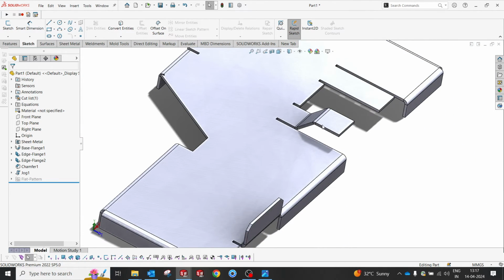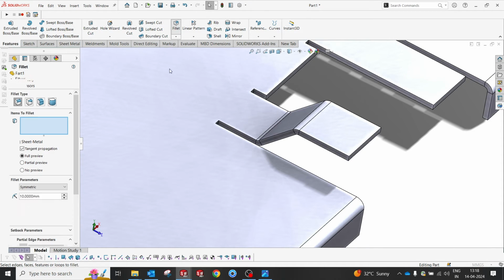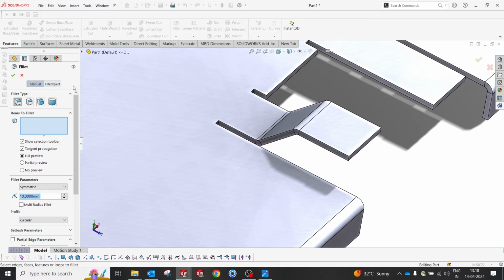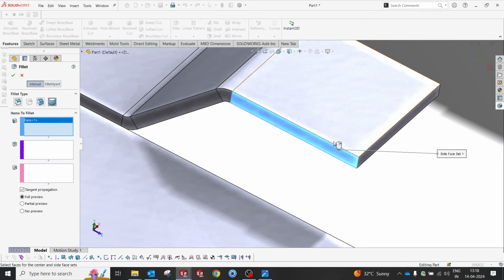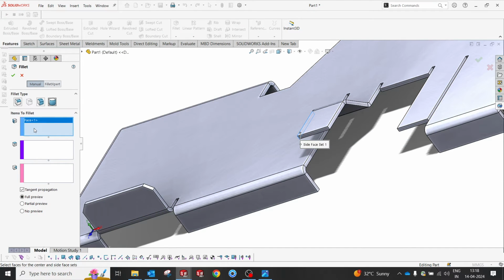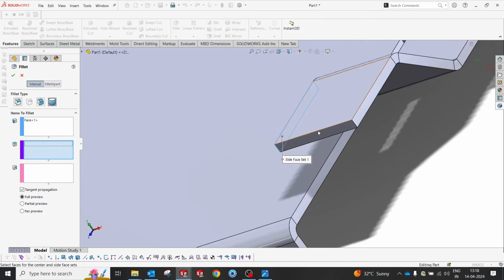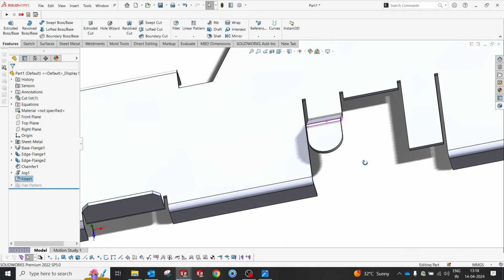and this is done now. And now I can make sure it should round the face. So I will go with this option, the last option. I have to select three faces to create such fillets. So one is the blue, one is the dark violet, and the pink, so that the radius will get formed on this tangential face. So hope this is clear now.